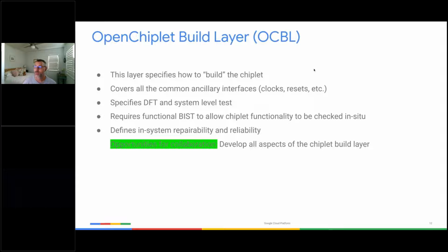Sorry, this is Joe. This is my area of expertise. There are a couple kinds of BIST. The first is logic BIST, which uses pseudo-random patterns. By the way, you could do a checksum of those patterns and get your encryption key, or be able to tell if the netlist has been messed with in any way.